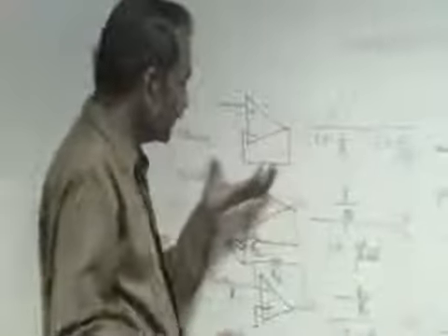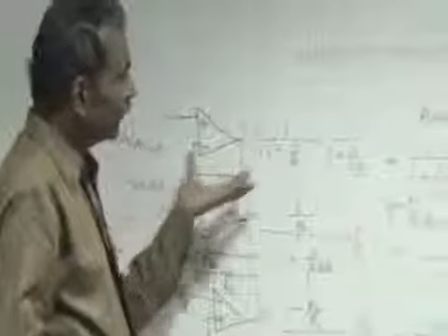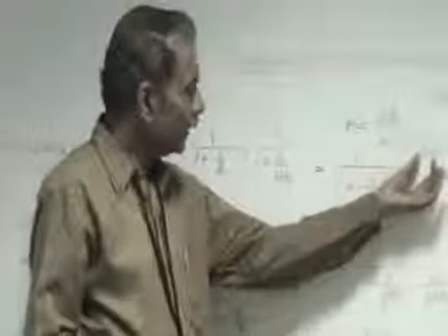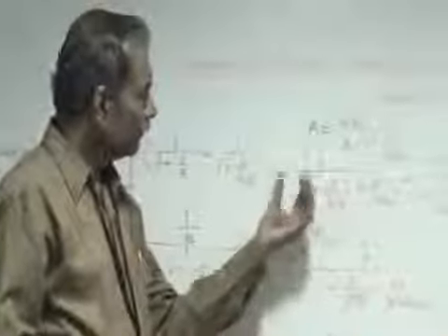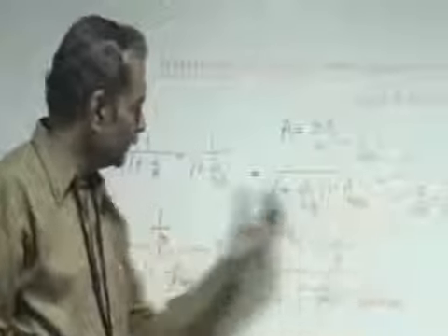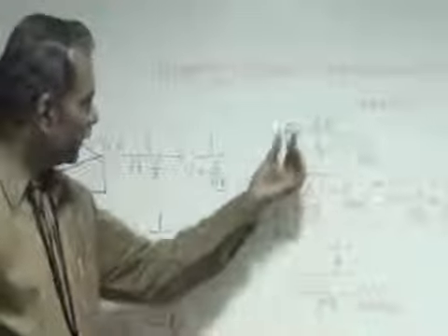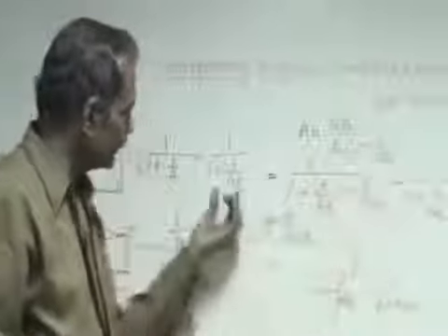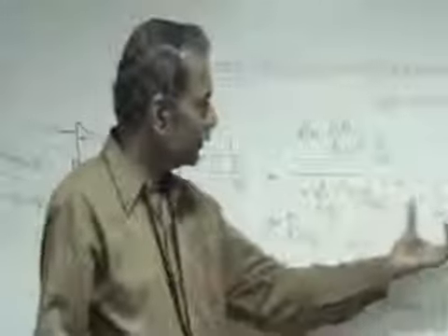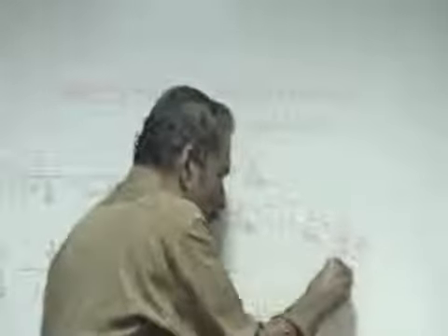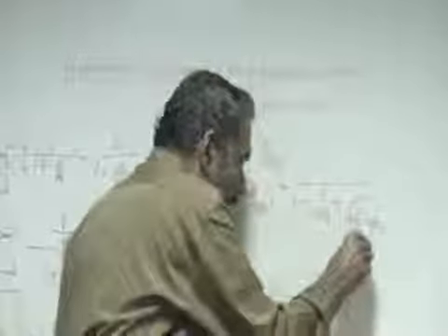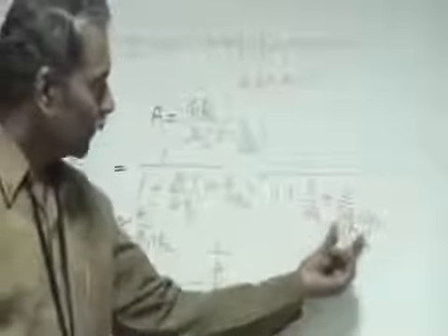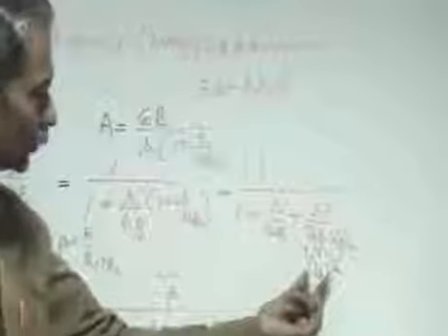So in this experiment, we are obtaining the frequency response of the feedback amplifier with both gain bandwidth product and the second pole taken into account. It becomes a second order system like this, and GB is replaced by GB divided by S into (1 plus S by omega D2), and you get transformed to a second order. In the second order equation, this is called the natural frequency of the system. The coefficient of this is omega naught square.